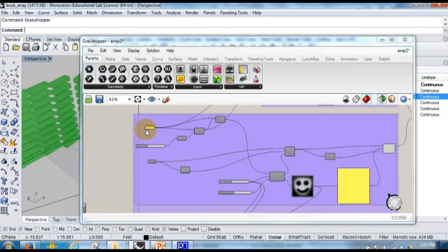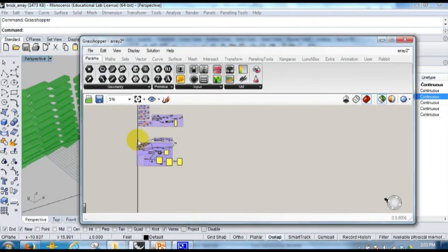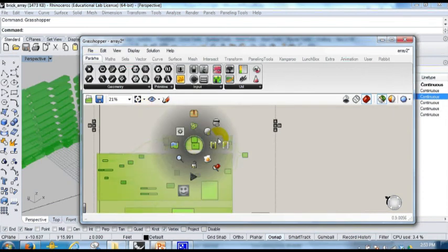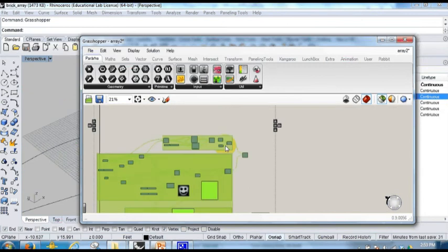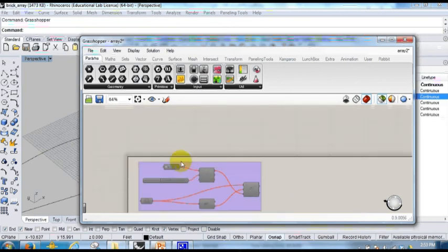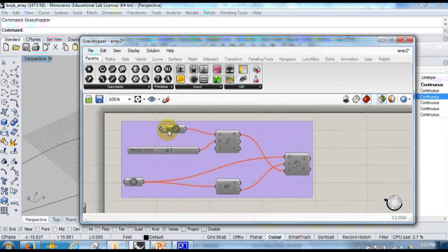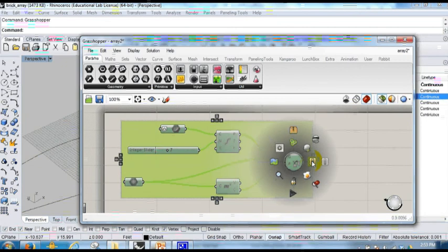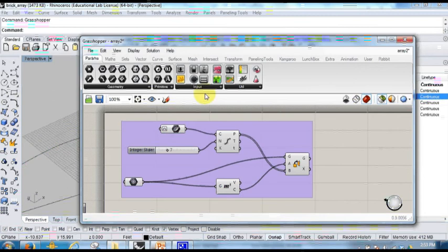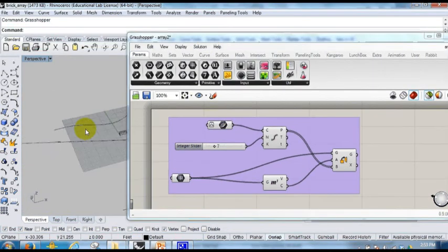So in Grasshopper, if you want to do this kind of operation, let me just disable everything. Click this guy, you can disable the component. So basically, it's like a freeze. It does not compute anymore. It became gray color. I will show you my first definition. I will select that, middle button click, and enable. So they will be computed. All right. I will explain this piece by piece.